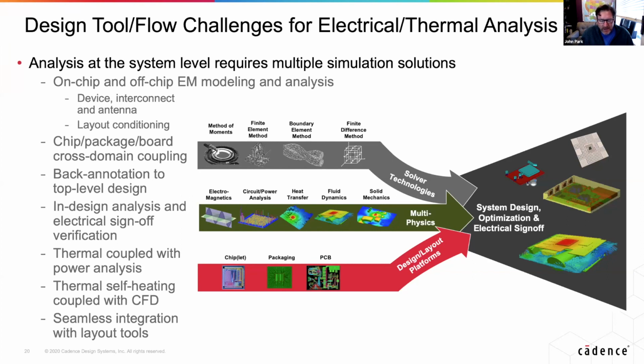So you need tools that are planar in nature that can give you the inductance of a coil inductor in a minute or two, and then you also need a finite element full wave EM tool for signing off more complex types of structures. And so you need almost a suite of different electromagnetics, RC, EM extraction capabilities, depending on whether you're working on chip, off chip, system level, whatever it might be.